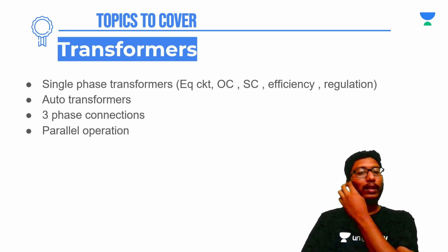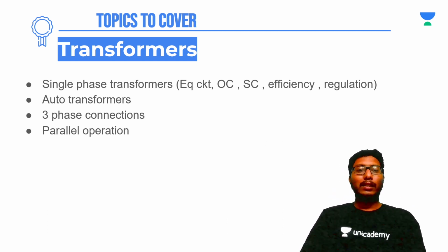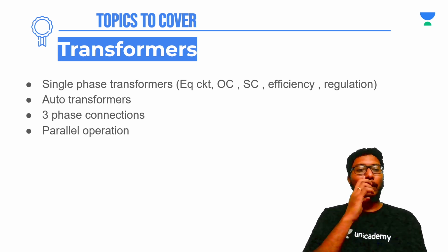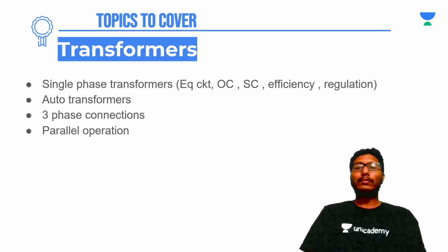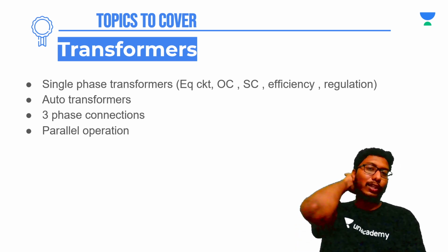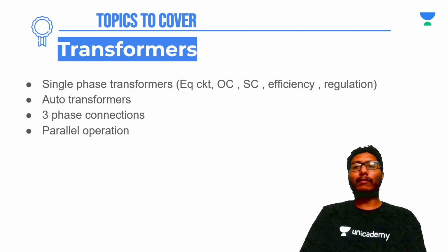And also, if the voltage ratios of two transformers connected in parallel are not the same, then there will be some circulating current at no load. You will be required to find this circulating current as well. And sometimes you will be asked to find the short circuit current, IA, IB, and the load shared by each transformer. For that, you first get the current supplied by the transformer, and you multiply that current with the line voltage.